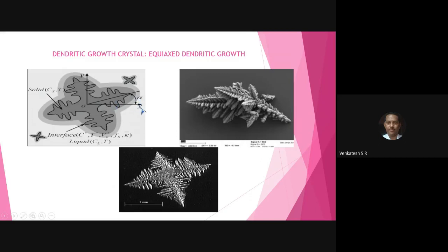It grows in size in direction X and in direction Y, and this is the center O, attracting the neighbor nuclei and growing in size. This is the diagram for dendritic growth of the crystal. Equiaxed dendritic growth. Equi means the same dimension, the same length in two directions, X and Y. Equiaxed dendritic growth. Remember, dendrite.